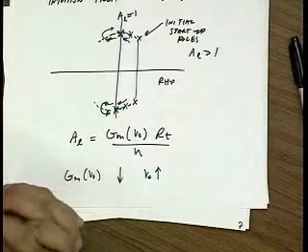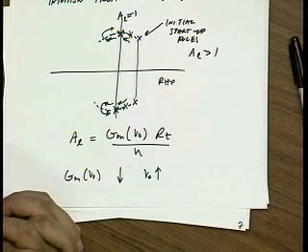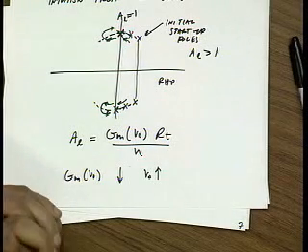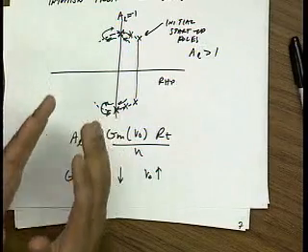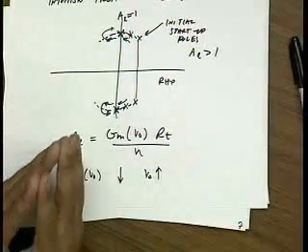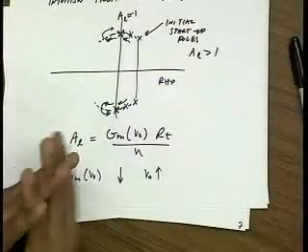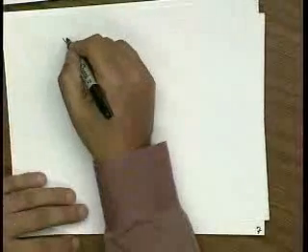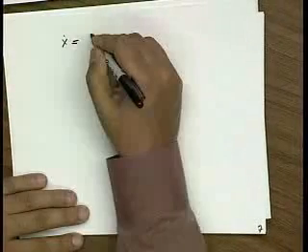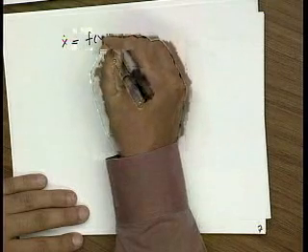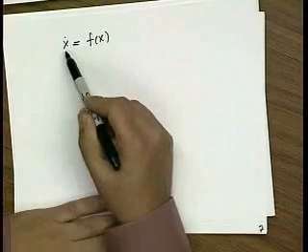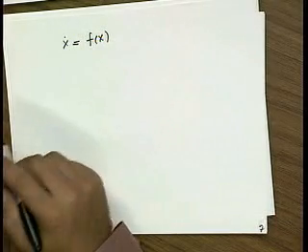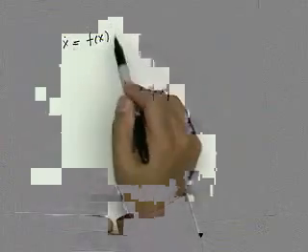If you study nonlinear circuits in more general terms, you can think of the oscillation as being an equilibrium state. From a mathematical perspective, your system can be described by x dot equals f of x, right? Where x is the state of the system. This could be the charges on the capacitors and the currents in the inductors. And f of x is some general nonlinear function.